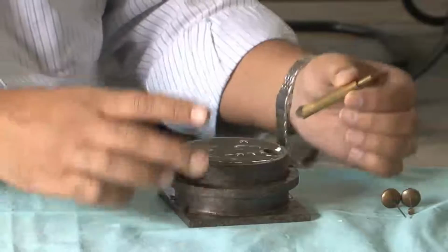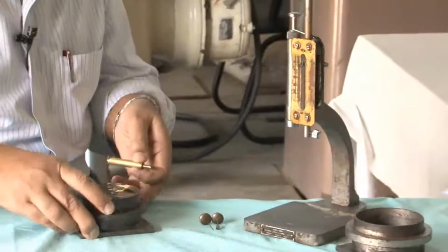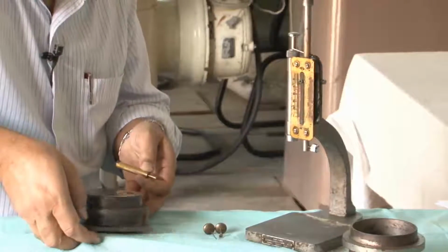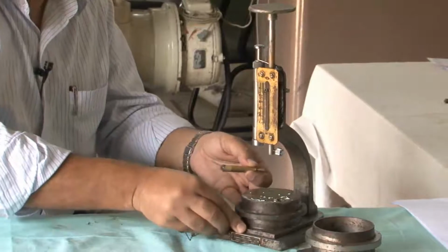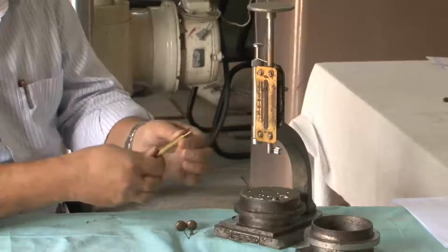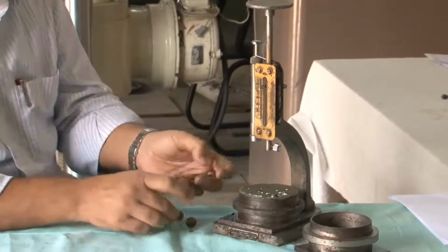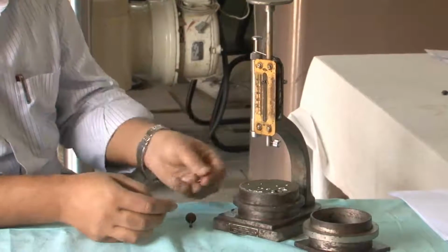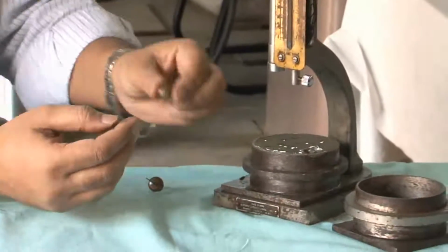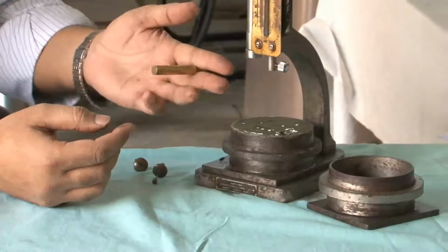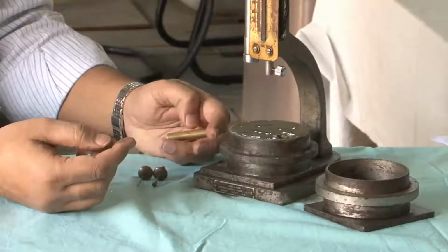What we use is a Vicat apparatus which is shown here, and what we do is to place the cement sample something like this and use these different plungers. It could be a plunger, it could be a needle like this, or it could be a very special type needle which is like this. These are used for consistency, initial setting time and final setting time.